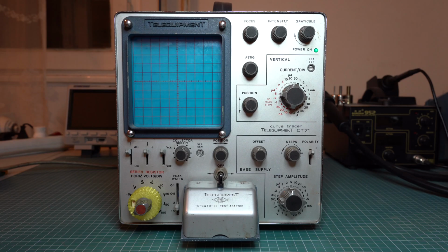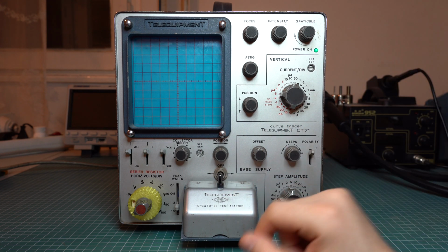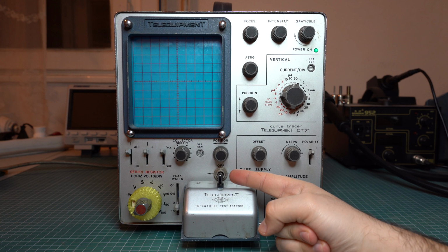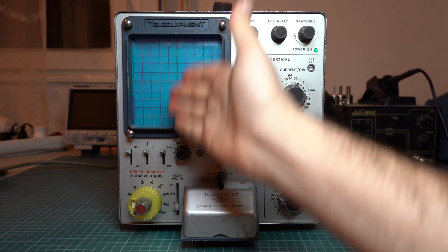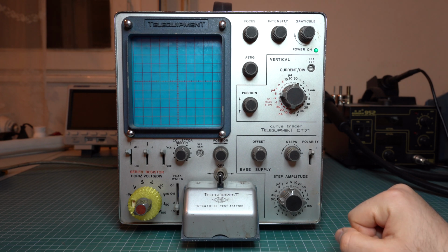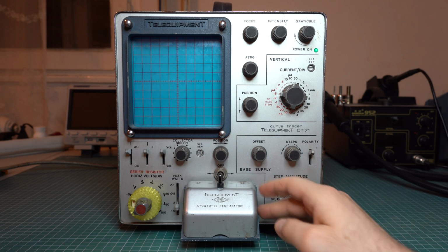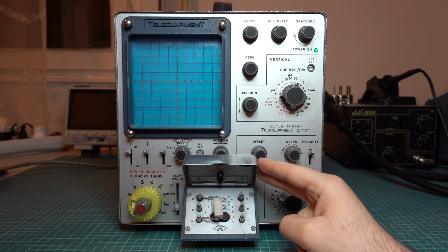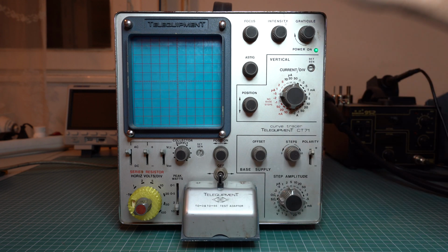And now you're probably thinking, well, if only there was a piece of test gear that could make those graphs automatically. Well, it just so happens that I have one, and that is called a curve tracer. We can use the curve tracer to see the current with respect to voltage. So you have the current on the vertical axis and the voltage on the horizontal axis. So if we think about Ohm's law, for a resistor, we should get a straight line, right? Let's see if that happens.